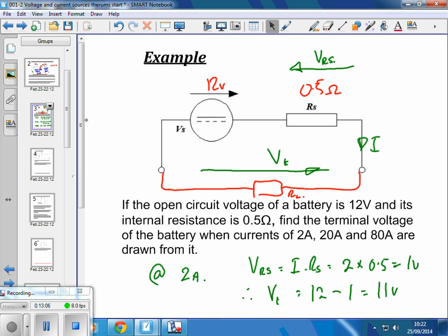Okay, you can get power supplies that will give you a constant voltage, but what they're doing is they're using internal electronics to sense what the terminal voltage is and vary the source inside to keep a constant voltage. You can also have constant current sources. What you absolutely can't have is a constant current and voltage source. It's not possible with varying load.